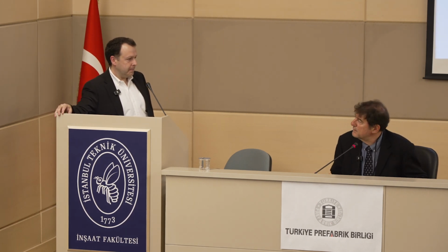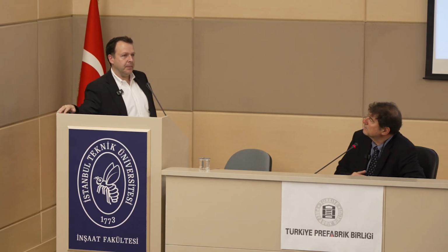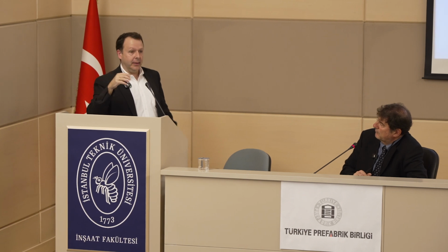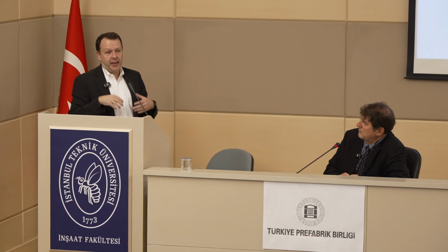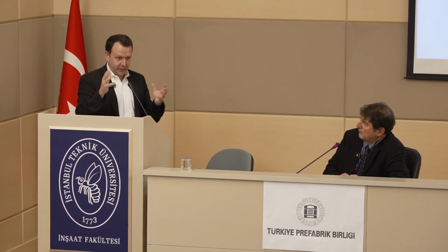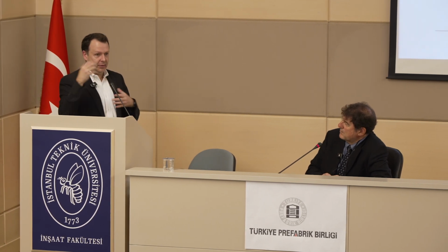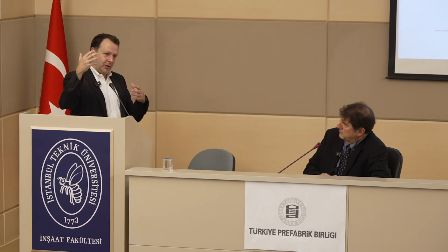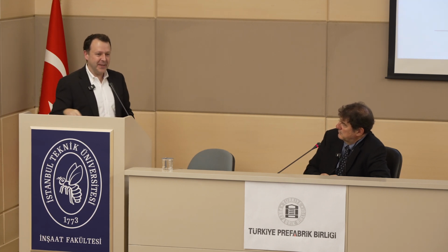Sure, if I understand the question correctly, yes. So the first question: if you go back to the SSRP report, the target was also 1.5, and then the actual from the response of the building was closer to 1.59. That was one example, just to give you context. But you would expect to see slightly different changes in the real structure versus in your model. And a shift of about 15% is based on literature, based on intuition, but it's informed intuition.